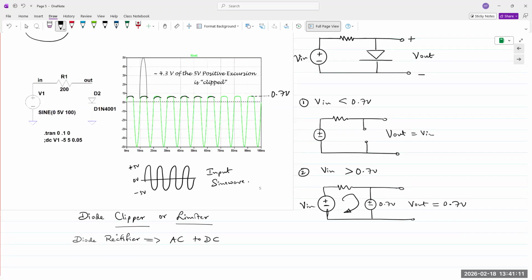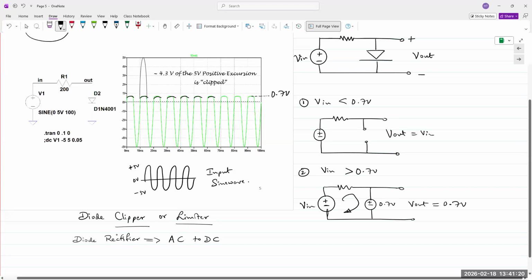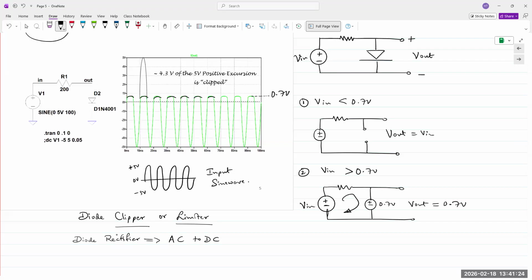And this is something that will come up in 315 or 3306. AC goes in both directions, positive as well as negative. As you can see here, you have either only positive or only negative, so it's only one direction. This is known as pulsating DC. It's not quite a flat line, but then we add a few more components, more specifically a capacitor.